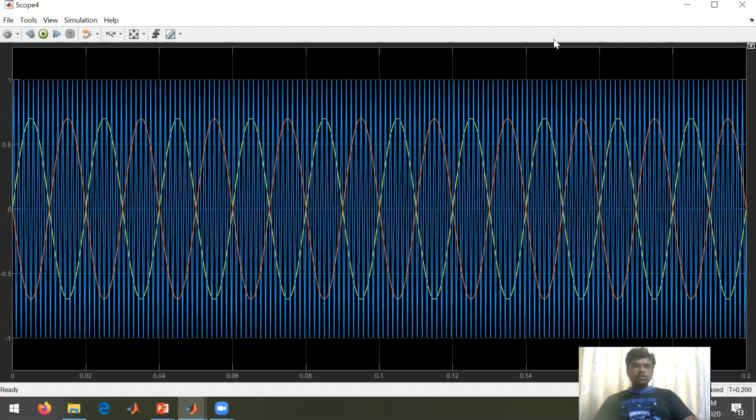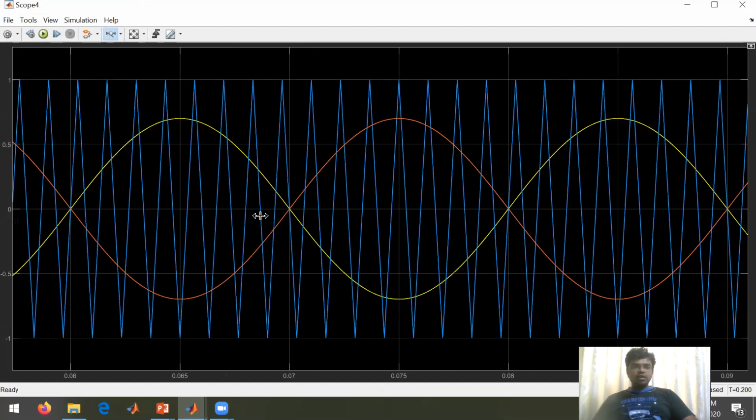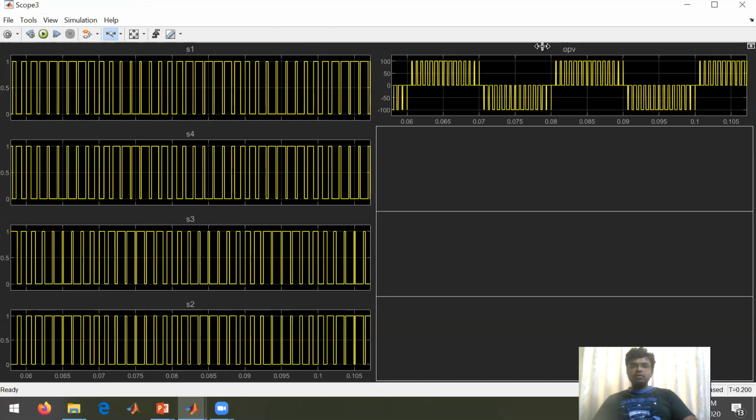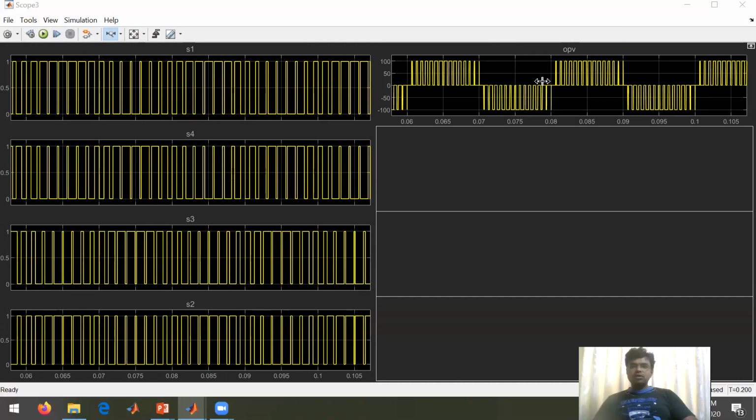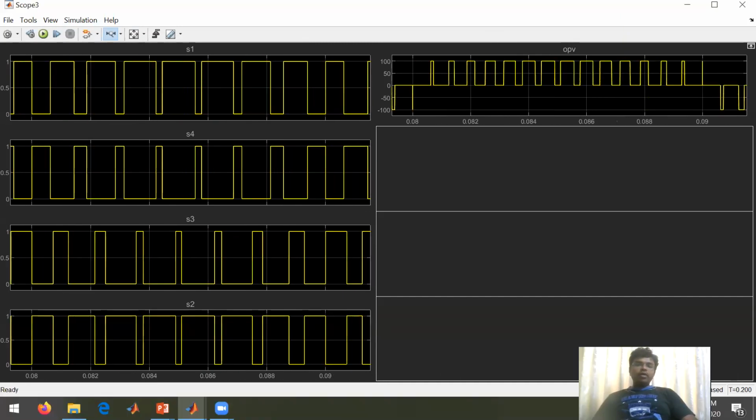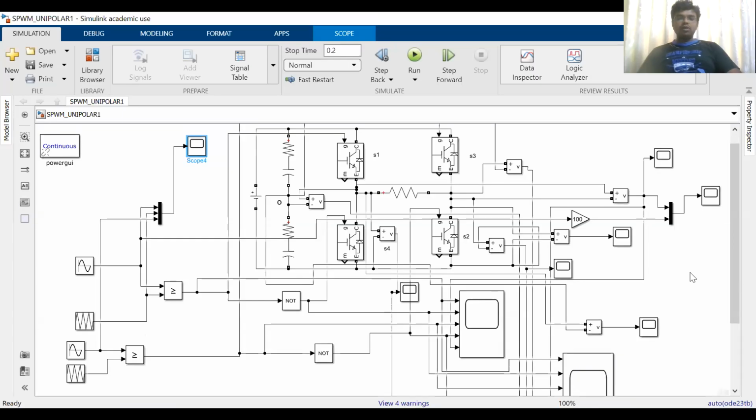If you observe, this is the screen, 180 degrees phase shift. Let us say this is 0 degrees phase shift, and this is 180 degrees phase shift exactly. These two waveforms we are comparing. That is generally the unipolar concept, right? And this is the output voltage concept, the output voltage switching frequency. Okay, right. So analysis is also important. I just want to show what exactly unipolar is.